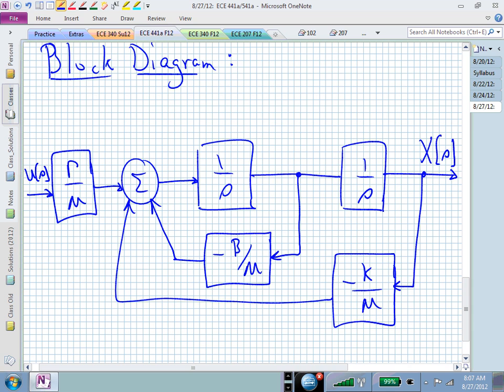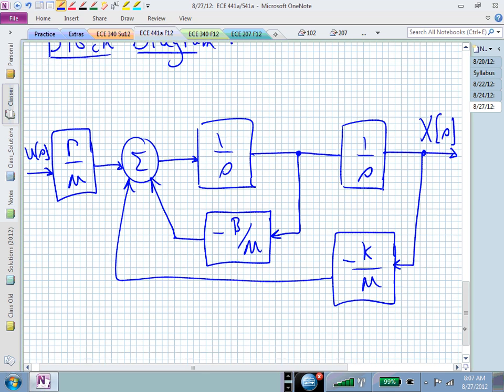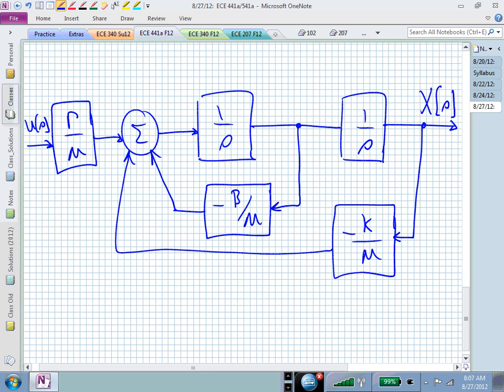And this was then the transform of our position variable, capital X. What we want to do now is from this block diagram, do some block diagram algebra and define the transfer function between U of s and X of s. So I'm assuming that we had this and we could obtain this from the differential equation. That would give us the all-integrator block diagram, and then we could take that into the frequency domain by replacing the integrator blocks with these 1 over s blocks, which are what they represent in the frequency domain.